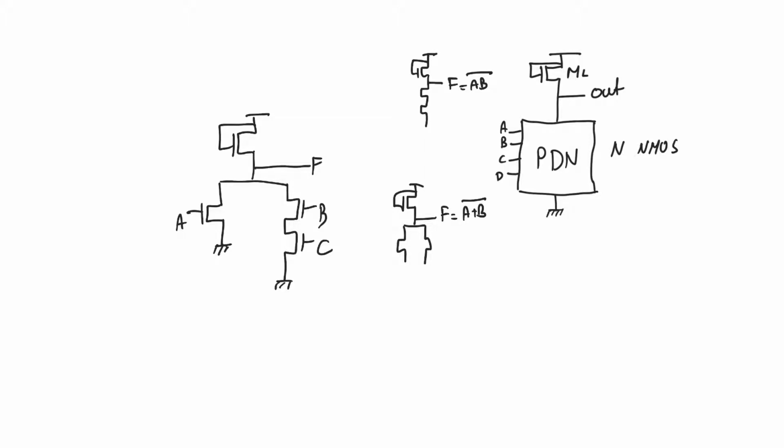And when we had two transistors in series in the pull-down network, we got F equals AB all bar at the output. So what seems to be happening is the function we observe at the output represents the connections in the pull-down network, where every series connection is an AND and every parallel connection is an OR, except that at the end there's also an overbearing, universal inversion that is applied to everything. And therefore the output of this logic gate is AB plus C all bar.